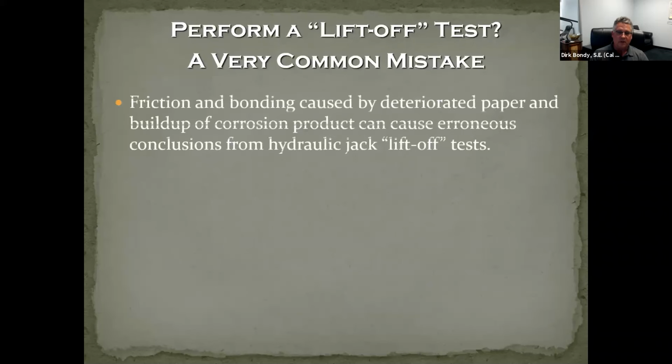Here's a very common mistake that I hope nobody listening does. Most engineers will decide in a post-tension building, if they think there's been a corrosion problem, to expose a piece of the pre-stressing, either at the end, somewhere in the middle, chip out an area and stress the tendon there, or go to a pour strip, somewhere that they can put a jack on and do what's called a lift-off, or try to stress the jack to see if there is tension in the tendons.